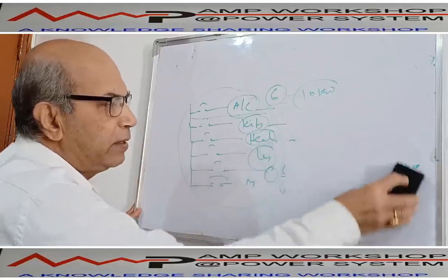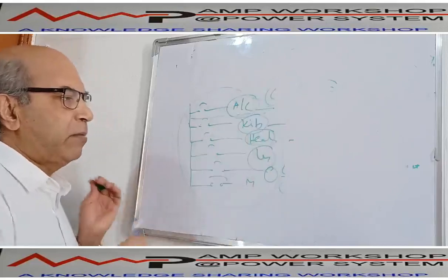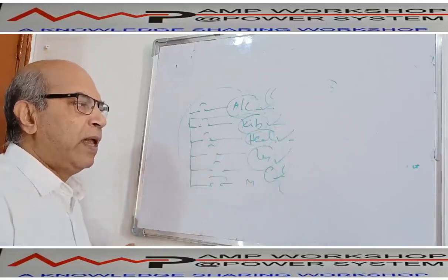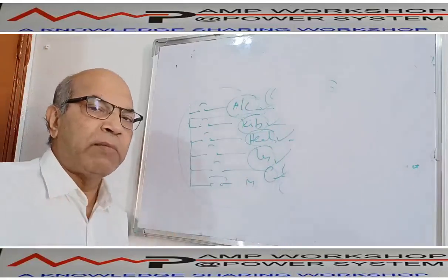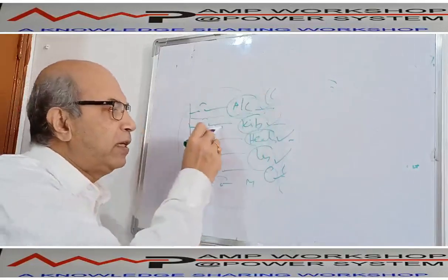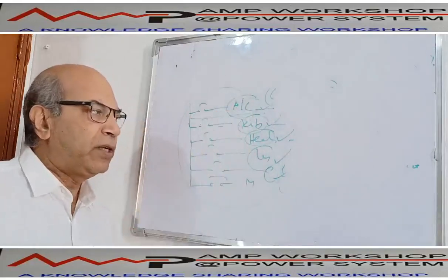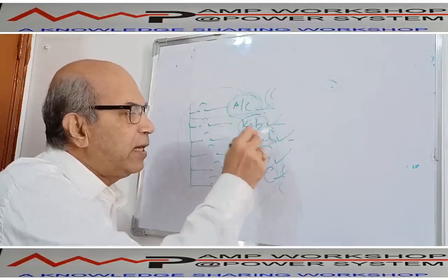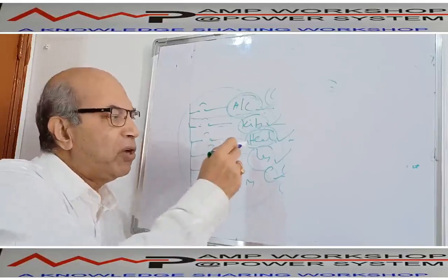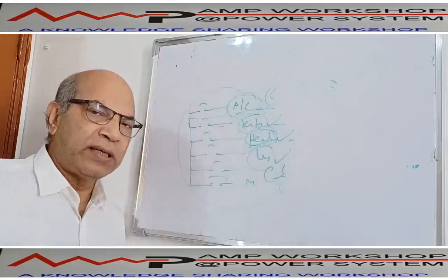When all the demand factors and maximum demands are decided, each subsystem has a maximum demand. Now all these maximum demands will not come simultaneously. There is a diversity in this. Suppose over 24 hours, when the kitchen is running, air conditioning is not running, or maybe one air conditioner is running and half of the kitchen is running. When the air conditioning is running, heating is not running, because heating and air conditioning are opposite to each other. Or when AC is not running, maybe in winter time, the water geyser is running.